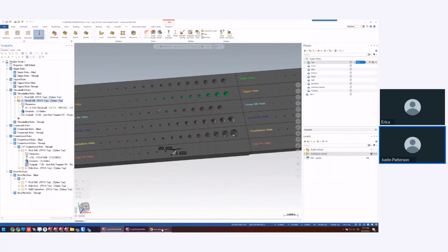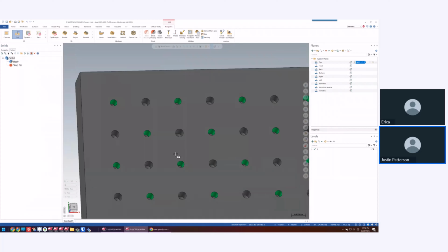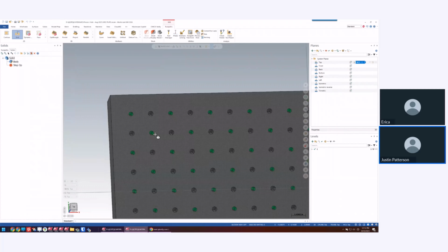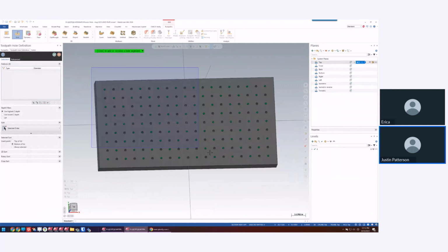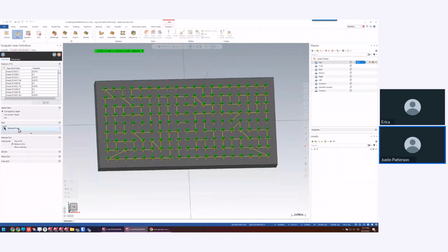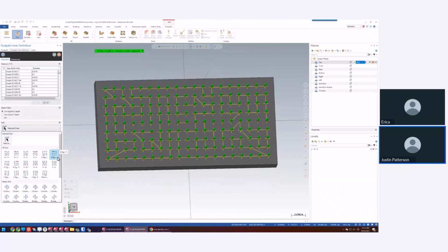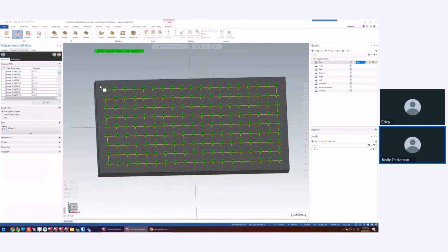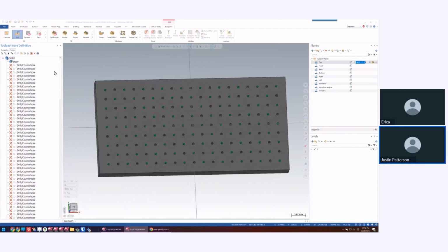Or a drill, which is actually the reaming of the holes. But this, again, I would come in here first before I even started anything and just window everything in. Let's just drill all these holes. Let's spot drill them all. You could go in one of these fashions. Let's say you want to go like that. That's the order. You could be a little faster at that, right?